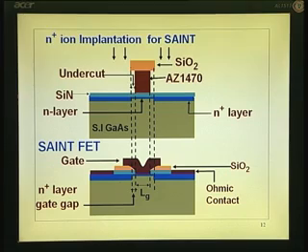Okay. So, the key thing here is to have this layer closed. One thing, it reduces the resistance that comes between the gate and the drain, the ohmic contact. The other thing is the velocity overshoot effects are felt very well. Okay. So, the technology involved is a little bit complicated. Now, let us take a look at how these devices perform.